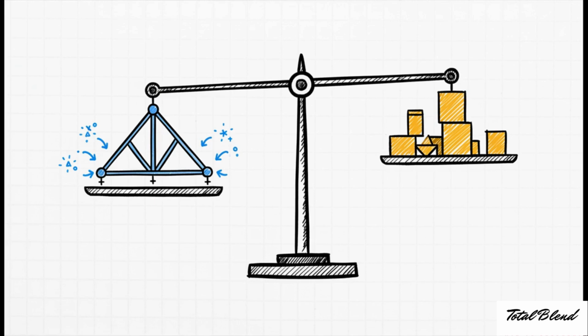So we plug that in. On the left side, we get 3 times 3 plus 3, which is 12. On the right, we have 3 times 4 joints, which is also 12. And what do you know? 12 equals 12. They're perfectly balanced. This frame is officially statically determinate.